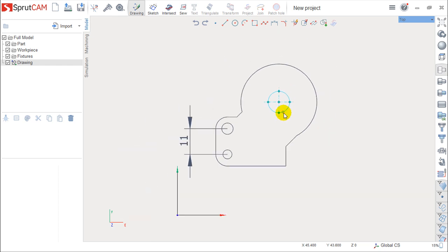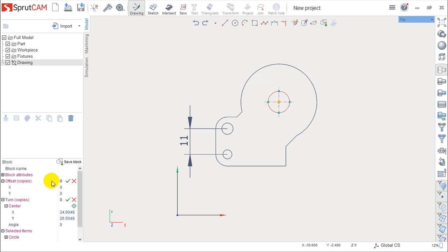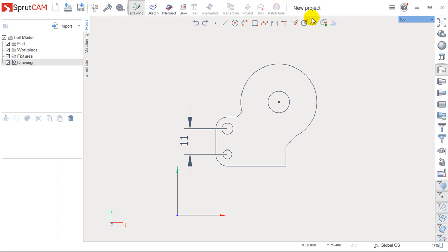I can do a couple of nice things also, like creating blocks. For example, let me create a point that for some reason I deleted. Oh, this one I don't want. I can, for example, choose this thing here. I can save it as a block, and now I have a function in the end, Manage Blocks. I can select my block here and just place my block where I want. So very easy also to do this.